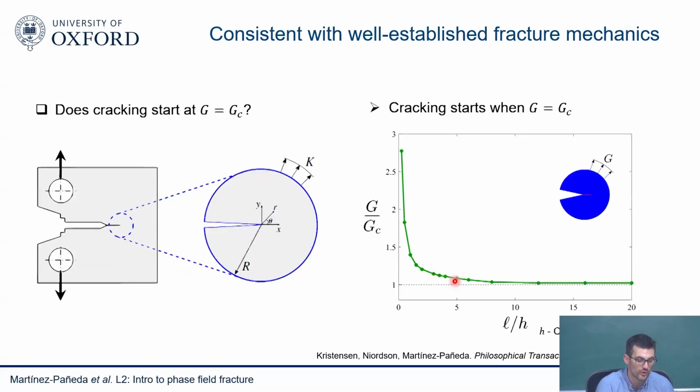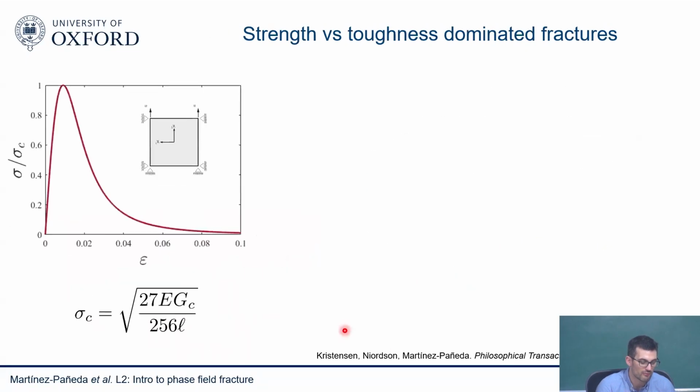And then of course a good question is, the original phase field model gives you this formula. Is this the right formula? Is this the formula that relates the fracture process zone to strength, or is there a better formula? Should I follow something like this, or should it be slightly different? I mean, that is up for grabs. It's a bit difficult to correlate. We know roughly it's the right approach, but there are other phase field cohesive models. The differences are small, but I'll discuss them later. But yeah, you could say every time I need to do it, I'll just apply this formula.